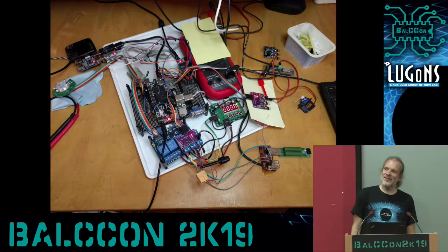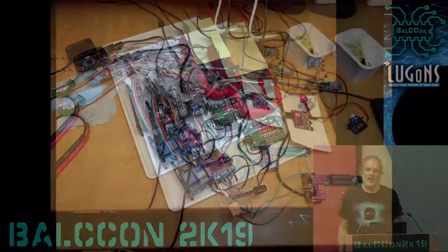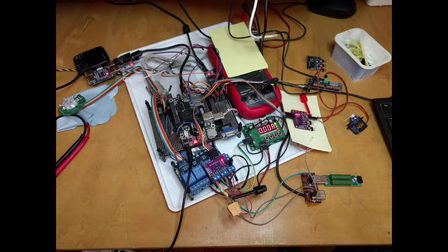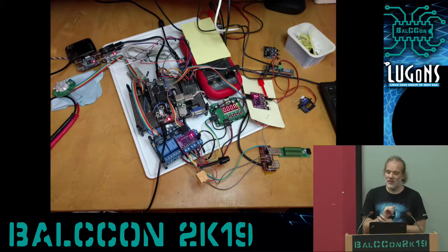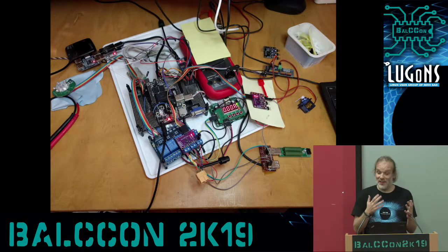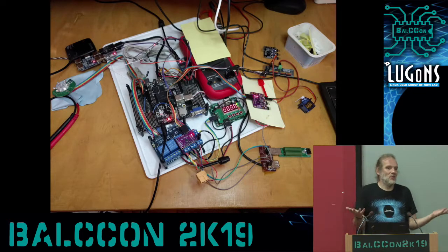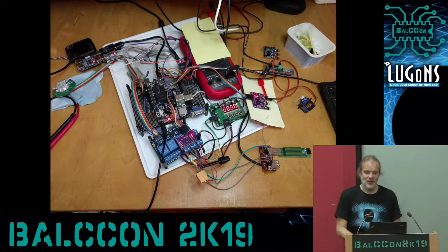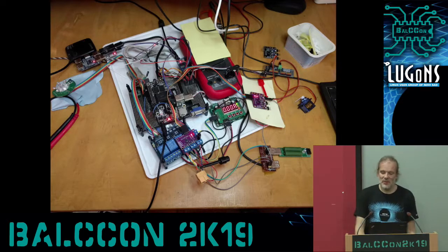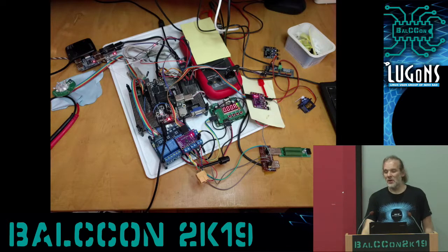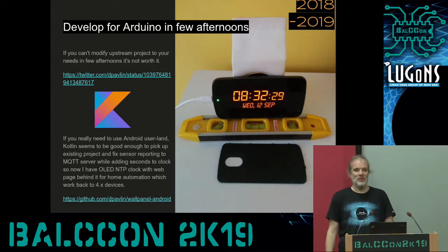And this is the current state of that CubieBoard you saw before. This is basically my bench power supply, which has 4 relay-controlled outputs, has open source firmware on the step-down converter on the right below the multimeter, and has the multimeter connected through serial to this box, which enables me to control and measure the voltage and current I am feeding to my devices, which was very, very useful. And this is actually a single-core A10, so a device which you can actually borrow from some of your friends who are not using it. This setup proved very, very useful to me, so hopefully it will motivate you to do something.